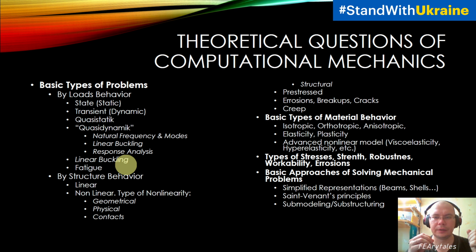Quasi-static is a situation when we have a very low speed of change of structure behavior or loads, and we can ignore these changes and solve any step as static, because we don't have any transient response, any bifurcations, any oscillation, and so on.